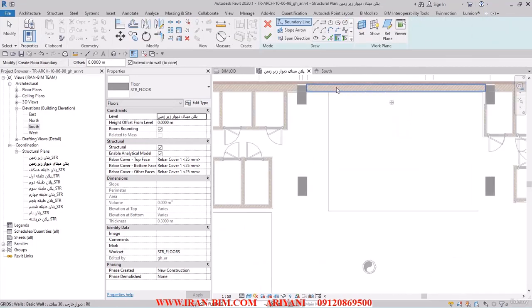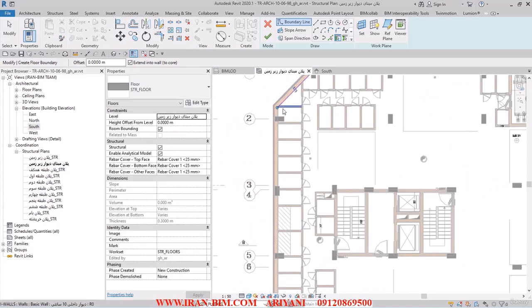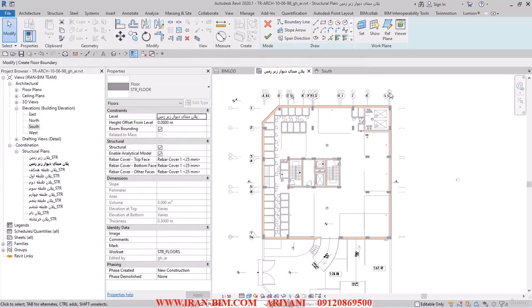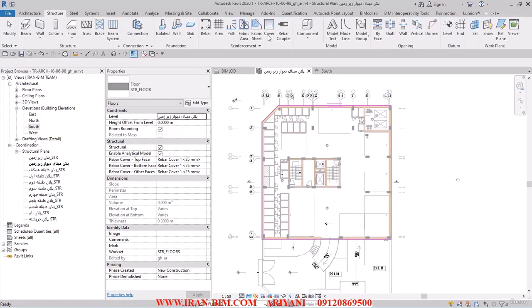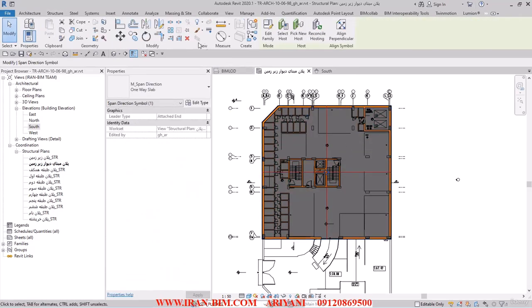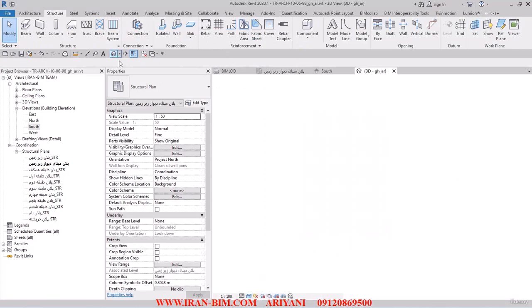So I select the pick a wall tool. We set the wall all around the plan that we have here, like this and here. Let me just take a look at it. So let's select all of this and then delete. I select the outside brick wall in here. So I trim these ones in here like this. And after we've done that, I finish it up. We'll delete the expand direction that we have here because we don't need it.